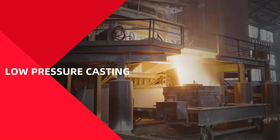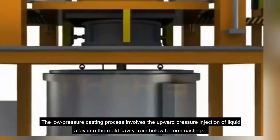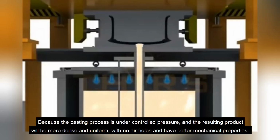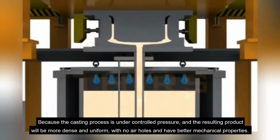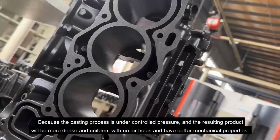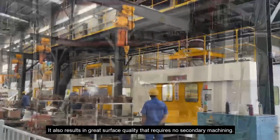Low-pressure casting. The low-pressure casting process involves the upward pressure injection of liquid alloy into the mold cavity from below to form castings. Because the casting process is under controlled pressure, the resulting product is more dense and uniform, with no air holes and better mechanical properties. It also results in great surface quality that requires no secondary machining.